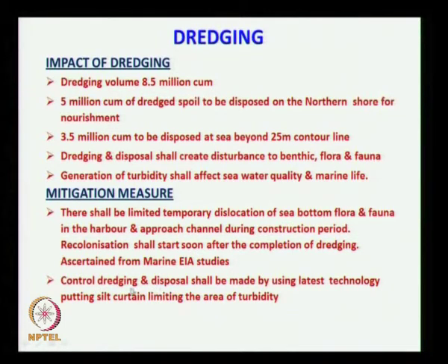This control you have to do for dredging and disposal by using the latest technology, putting a silt curtain to limit the area of turbidity. If the material is sand the turbidity will be less; if it is a clayey material the turbidity will be more. Mostly in Gopalpur it is a sand material, so the turbidity will not be a problem.